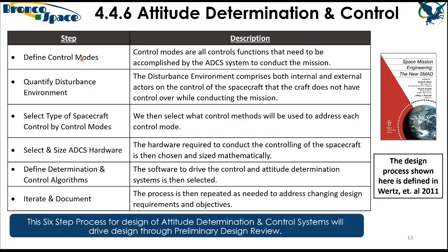The electricity flowed in a loop around this wiring, and that ended up creating a very weak electromagnet on the spacecraft that, when it interacted with Earth's magnetic field, caused the spacecraft to go out of control and spin up to a hilarious speed of 500 degrees per second before they were able to get it back under control due to some cunning control engineering. But stuff like that you have to watch out for. Next, you select the actual actuators, right?